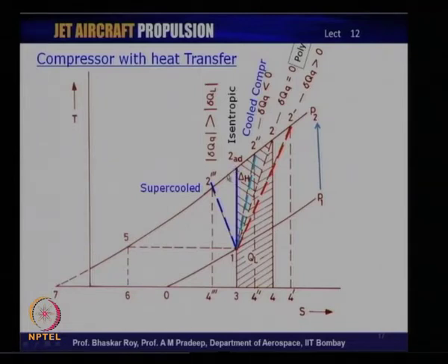In which case, for a jet engine purpose, that may not be a very desirable situation, because the flow from the compressor is going to the combustion chamber, and a supercooled flow going into the combustion chamber would require additional heating in the combustion chamber for the flow to be taken to high temperature. So, supercooling may not be a desirable phenomenon in a typical jet engine operation, but a certain amount of cooling, as we can see, is certainly a desirable phenomenon for a more efficient compression process.